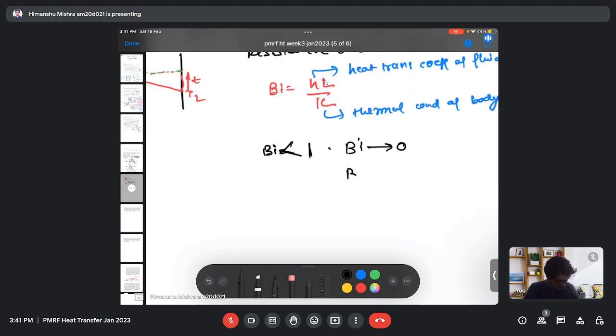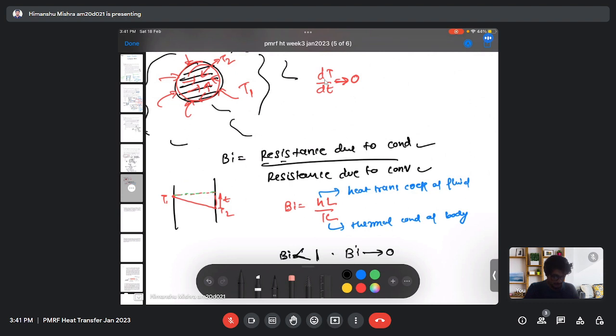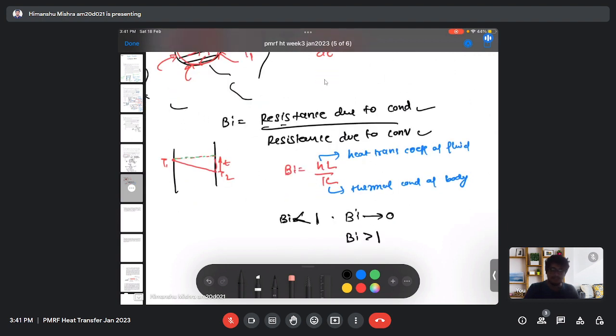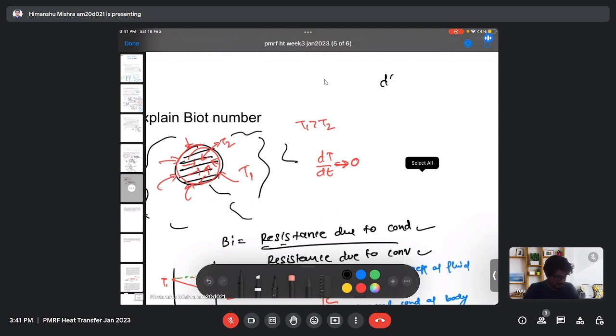On the other hand, if the Biot number is greater than 1, there is heat transfer from the fluid to the body, which takes some time. And inside the body also, there is a conduction process, which will take a significant amount of time to attain the uniform temperature. In those cases, we cannot use the lumped heat transfer concept. It will be very ineffective there. So we will use a different mechanism. Some of these mechanisms are to solve the governing equation, or use the Heisler chart, or use experimental correlations to determine the thermal conductivity or various properties of the material. So these are some indirect methods.